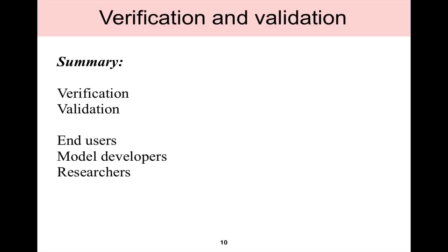So in summary, verification and validation. Verification checks the math of the model, that it's in alignment with the developer's conceptual vision of what it was supposed to be, using simple checks, energy balances, radiation calculations, heat transfer calculations, and so on. Validation, on the other hand, was shown as a comparison to real-world experimental data. Whatever that may be, this is helpful for seeing how well the model is approximating reality, how well it's performing